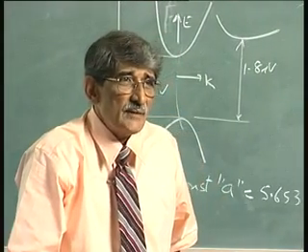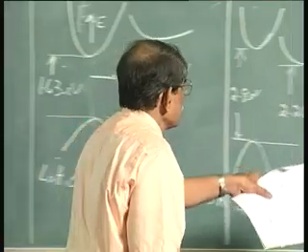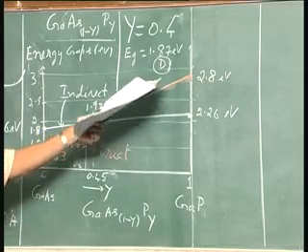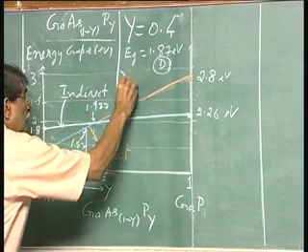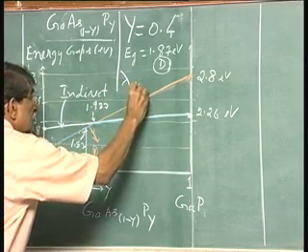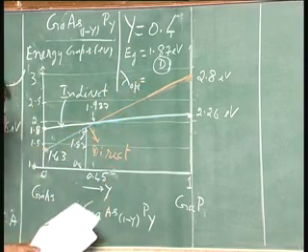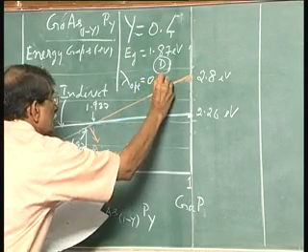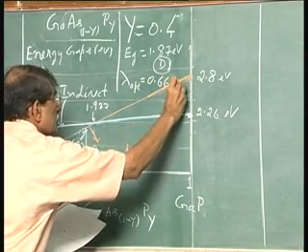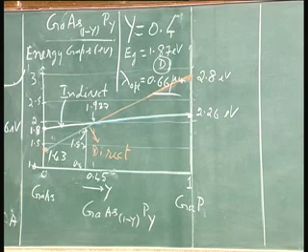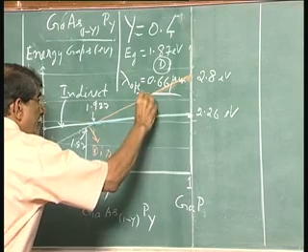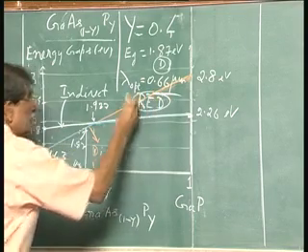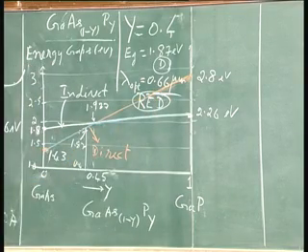What is the wavelength corresponding to that? 1.24 divided by 1.87, so many microns. So, lambda optical emission for this case actually turns out to be 0.66 microns. What is that? That is red light. I am overwriting here, but you have got red light.